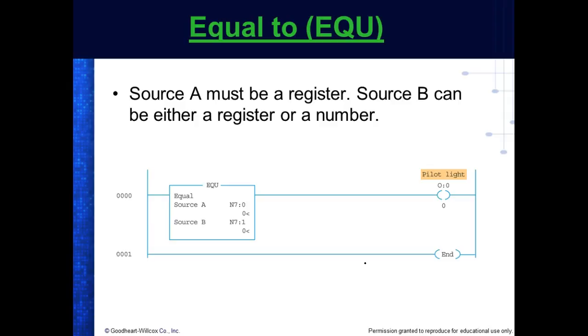So we've got N7 registers, we've got bit registers, so the B3 and the B10 registers are bit registers. We have R registers, which are control registers. We have F8s, which are what for microprocessor logic. R is logic. What's F8? The F8 data registers, those are our floating points.